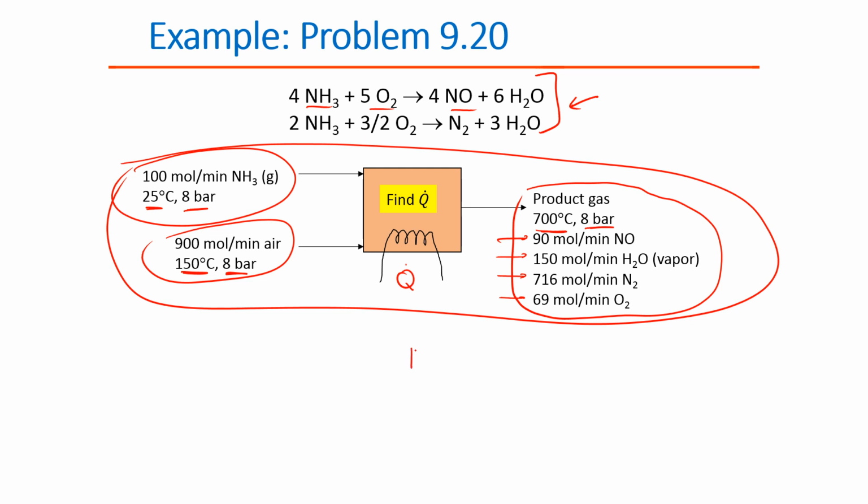Okay, so our reference species are just hydrogen, nitrogen, oxygen, and then carbon, and this will be graphite. Okay, so we'll look up in our tables for delta H of formation for all of these, and then add from our reference temperature to a final temperature, Cp dt. Okay, so that's how we're going to get the enthalpy for all of our different species. Okay, and then we'll calculate the required rate of heat transfer to or from the reactor. So we want to get the kilowatts coming in or leaving the reactor.